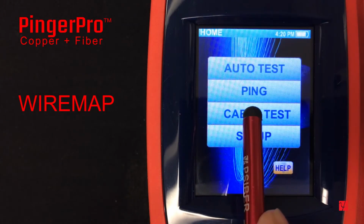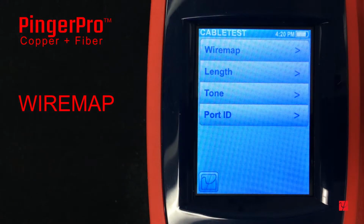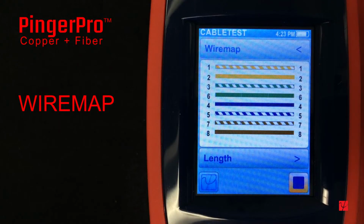Pressing the cable test button on the home screen brings up the cable test menu. The WIREMAP shows how the wires connect from one end of a cable to the other. There are 4 wire pairs in an Ethernet cable: 1, 2; 3, 6; 4, 5; and 7, 8. Each wire in the cable must be connected to the correct pin at the far end plug or jack with good contact in the termination.